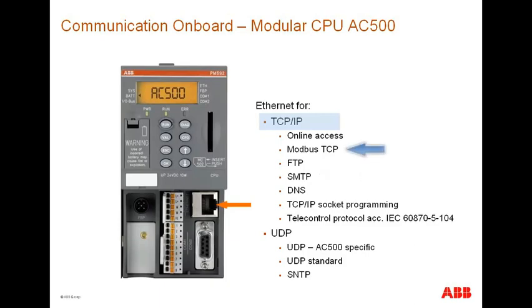Configuring this port for Modbus TCP functionality would enable us to exchange data with other AC500 controllers or with third-party PLCs, as a Modbus server, or client, or both. Also, by configuring the DNS function, the IP address of a remote host could be supplied by its name.